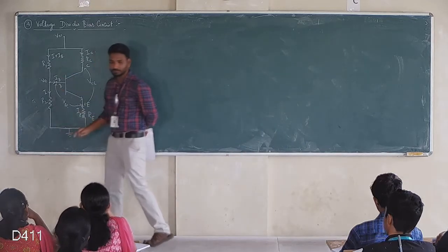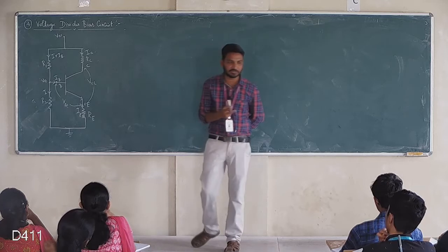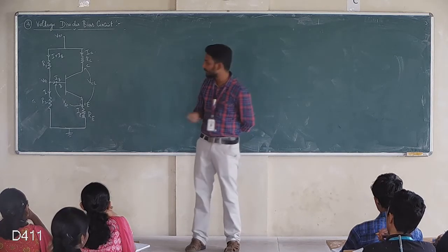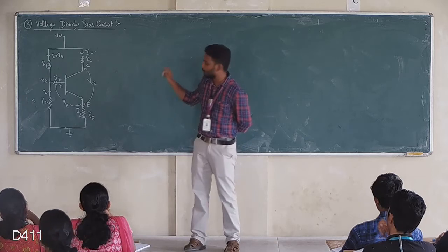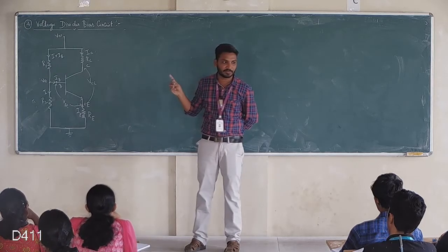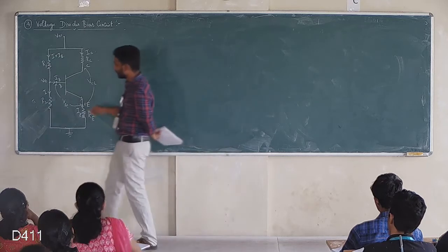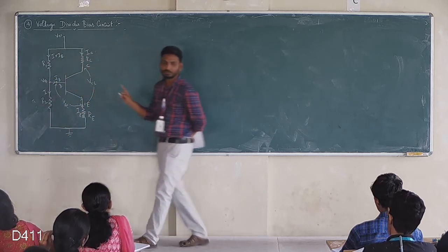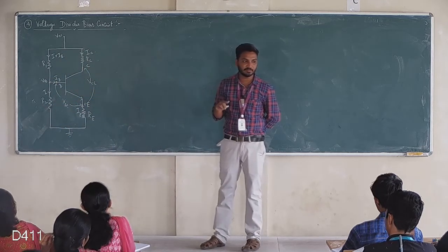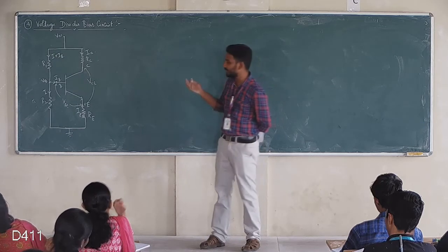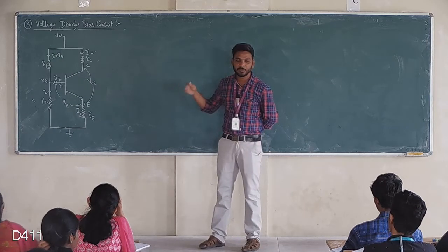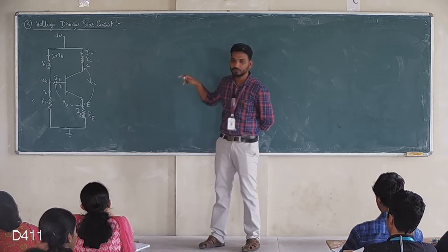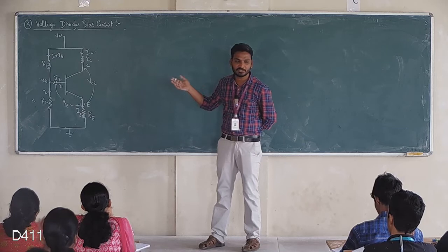Before, we wouldn't use two resistors for a voltage divider in the emitter bias or collector bias circuit, but here we will use R1 and R2. R1 and R2 are considered a voltage divider. It will provide one voltage, that is VB. This VB will compensate the changes in beta, so beta won't change with respect to temperature. By using the correct values of R1 and R2, we can control the compensation of beta.